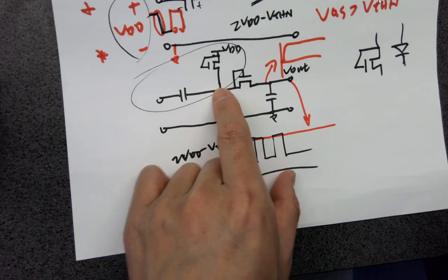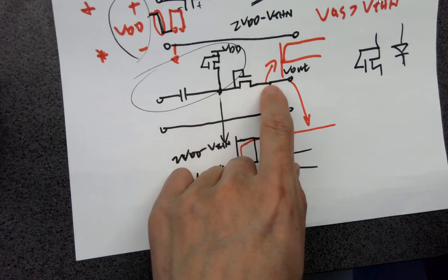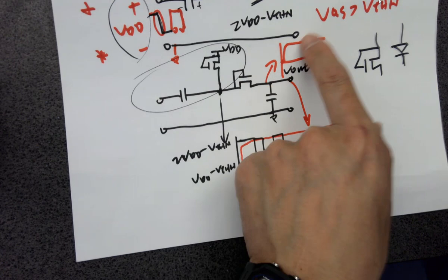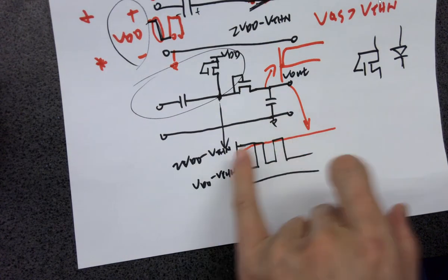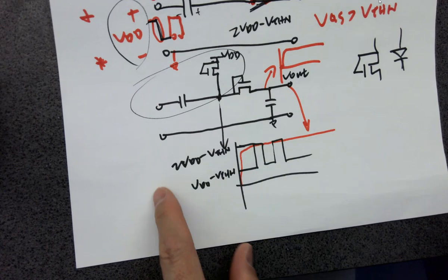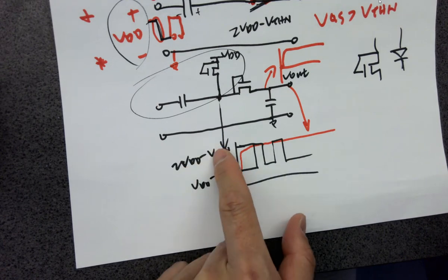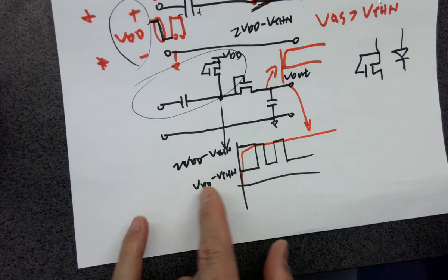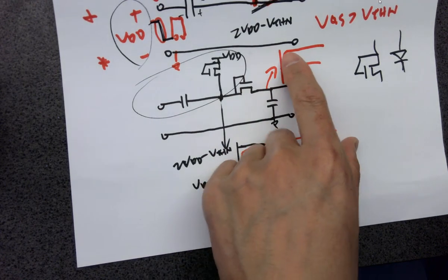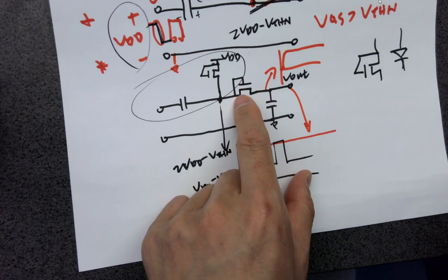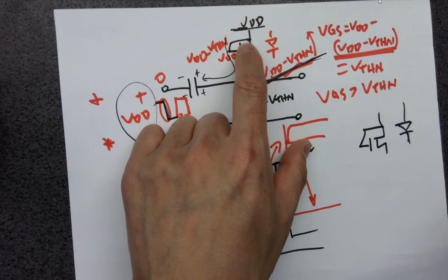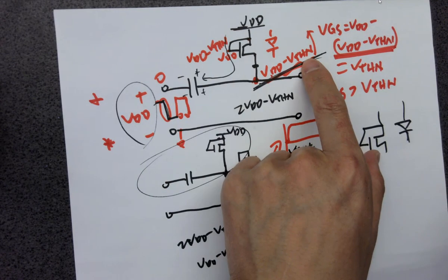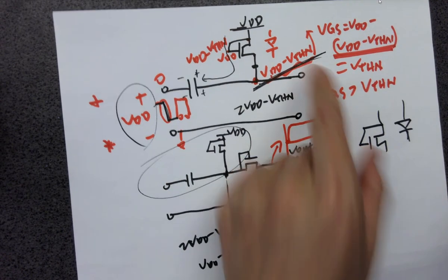Okay, and then it's going to pass another NMOS. So what is the DC voltage over here, if you are looking at the peak voltage? Because of the property of the circuit, it's not going back, it's eventually just staying at the peak voltage. But there will be a loss, right? And every time you pass through that NMOS transistor, you are losing 1 VTHN.